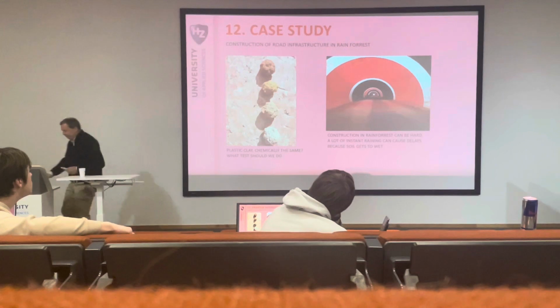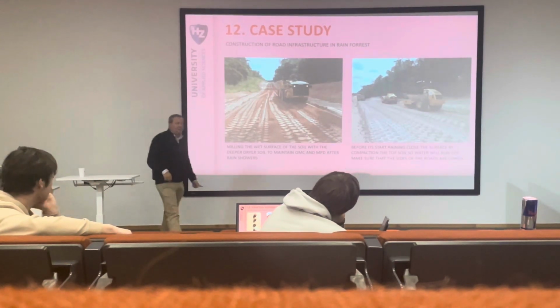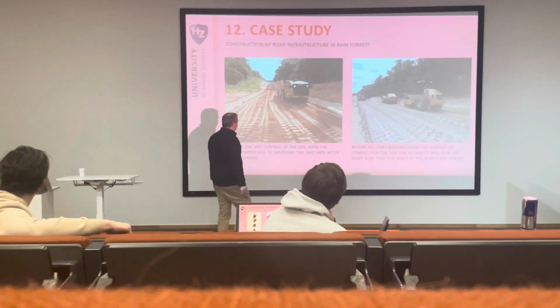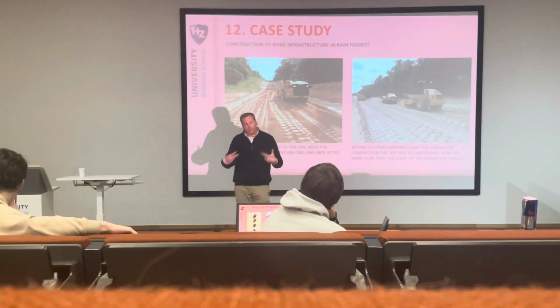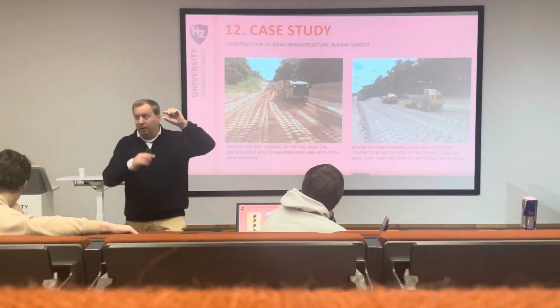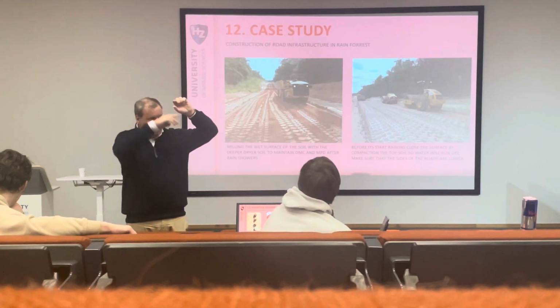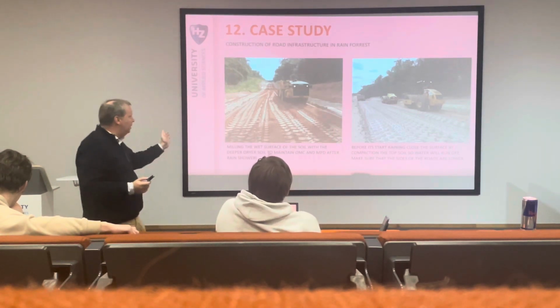Smart method, this one. Here you can see, with the technique that we use, nice clay. When you mix it, the clay becomes drier, because underneath that very wet top part you have a drier clay. By mixing it, you create an optimum moisture content. And then you add some cement.